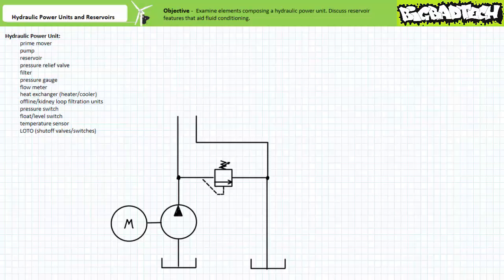an operator. You'll note that a hydraulic system may be illustrated schematically with more than one reservoir symbol. However, this simply aids comprehension. There is only one reservoir. Rather than untangling a mess of intersecting and crossing return lines, a single reservoir can be best illustrated schematically multiple times. Additionally, hydraulic power units often include a return filter.